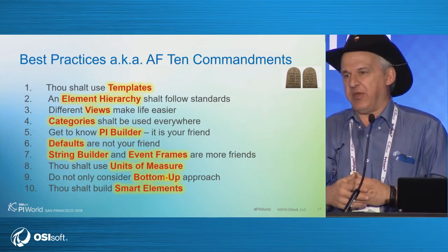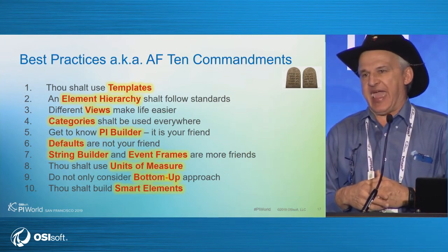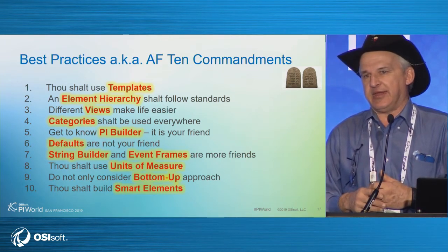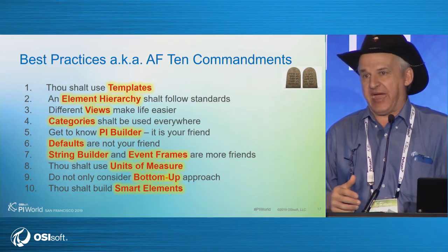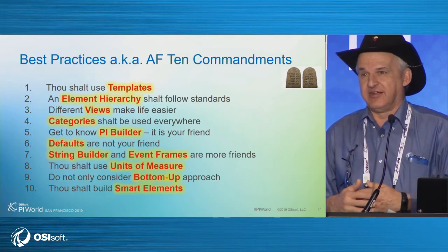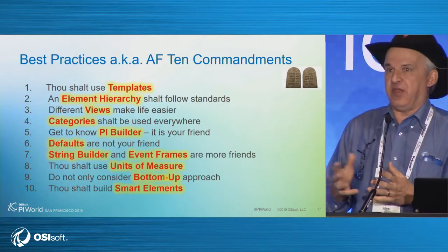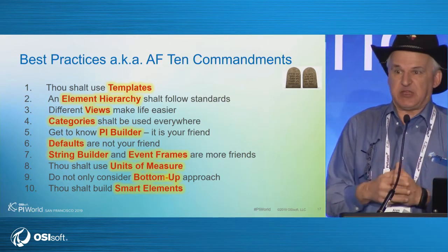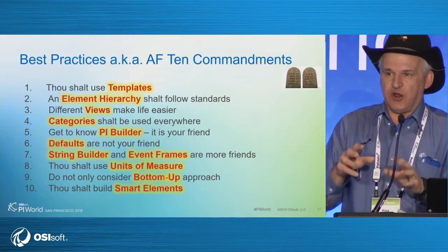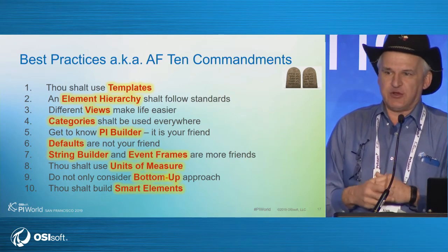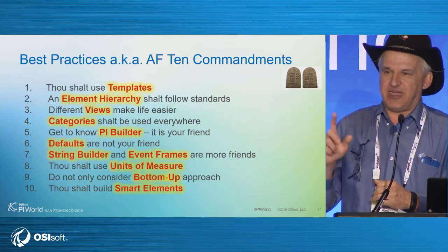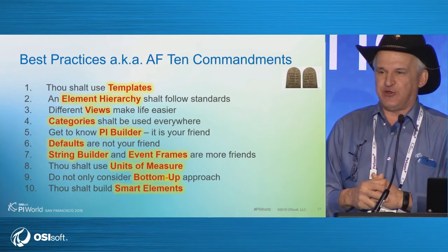Get to know PI Builder. So those of you who don't know what PI Builder is, that's an add-in to Excel that's also a replacement for the old SMT to build PI tags as well as AF structures. So those of you who actually build the structures in the PI System Explorer, well, that's great when you do one or two, but if you're trying to do 10,000, guarantee you're going to get really tired of clicking and copy and paste. It's not very useful. Okay?